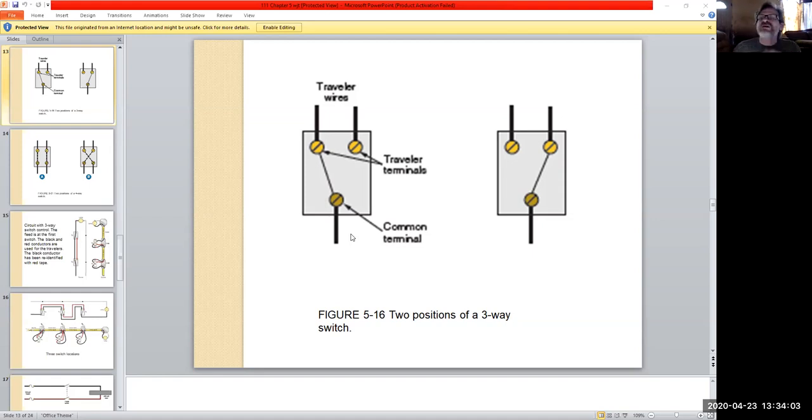So on my hallway light, I could flick the switch up, right? And it would turn the light on, but I couldn't go down to the other switch and turn it off. I always had to turn it off with that one. Either switch would turn it on, but I didn't control both back and forth. That's because they didn't use the traveler correctly.